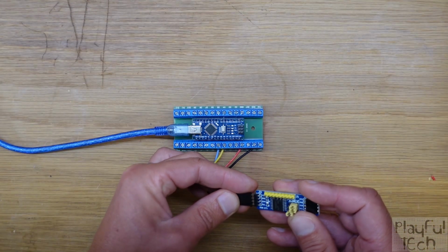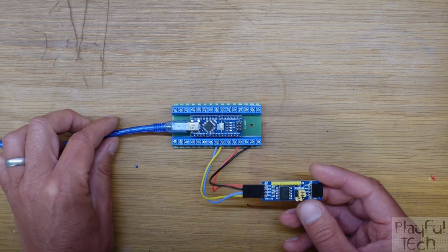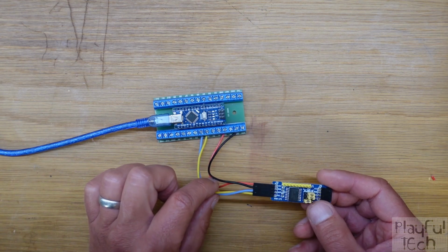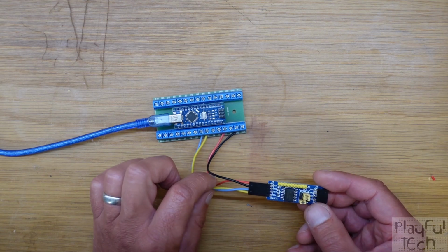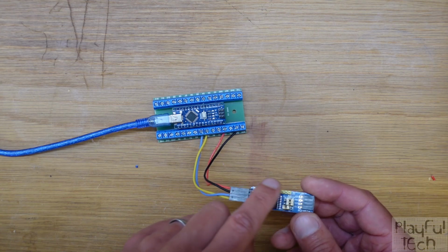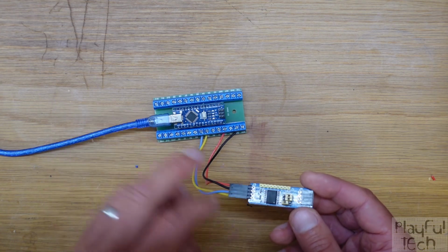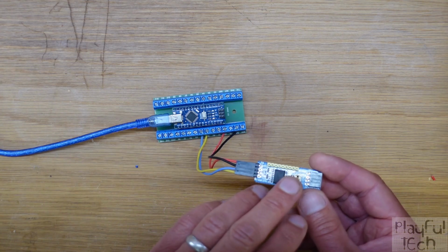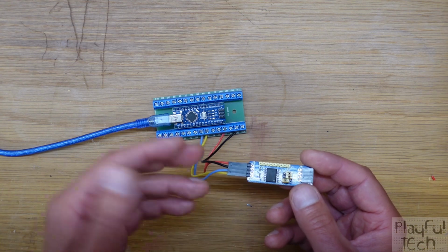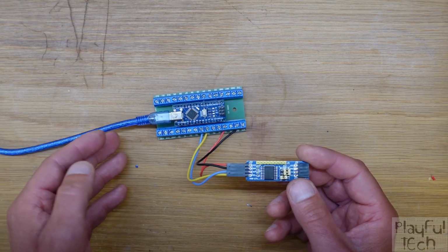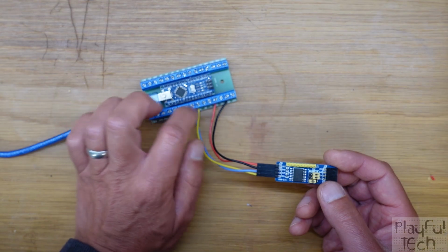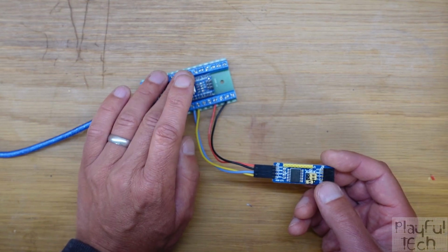So when I plug it in like this, the Arduino can send a message to the PCF8574 over the I2C interface here, and it can tell it to write a high or a low value to these pins. Or it can ask the chip whether the voltage at these pins is high or low. So they act pretty much the same way as if we were to do a digital write or a digital read to one of the GPIO pins on the board itself.